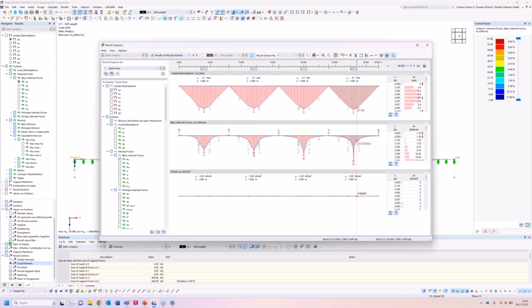In general, especially in reinforced concrete, you will put, let's say, 11 square centimeters per meter. Yes, so it's per meter. So in reinforced concrete, forces mostly are able to redistribute because there are a lot of safety factors in the calculation and they don't come from nothing.